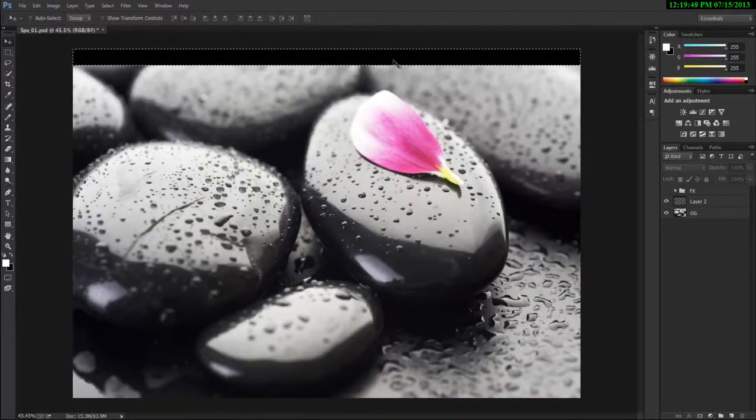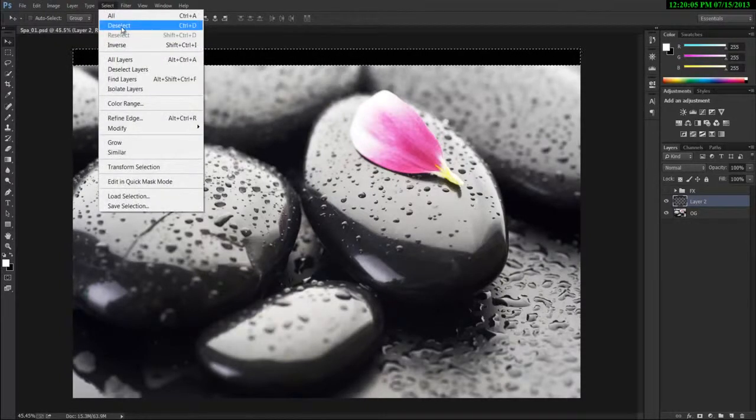And by the way, if you remember, right now I had a selection going on with my file. So I press Ctrl D for deselecting it. See, selections can always be moved around like this, but right now in this case we don't want to move our selection, right? So in order to deselect what we have selected, we can go to select and take deselect. But it is better to use a keyboard shortcut, so Ctrl D, because this is one command that you'll be using a lot.